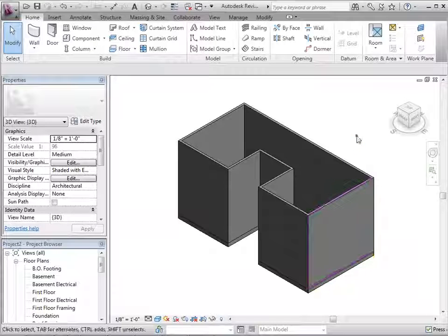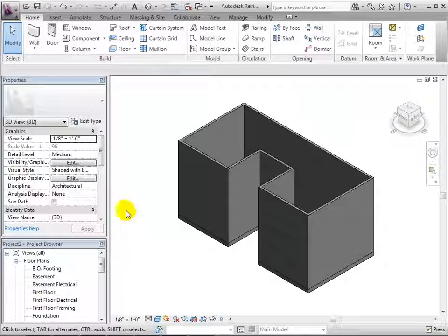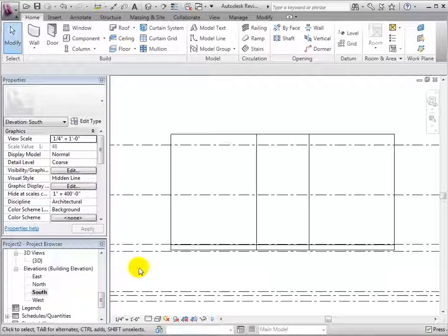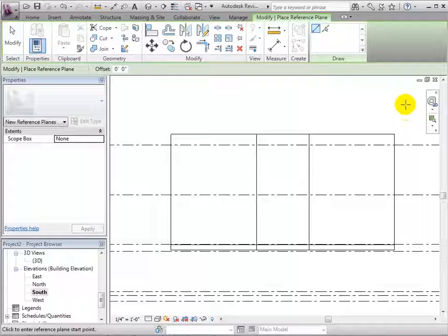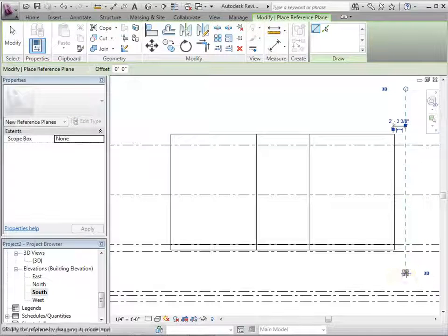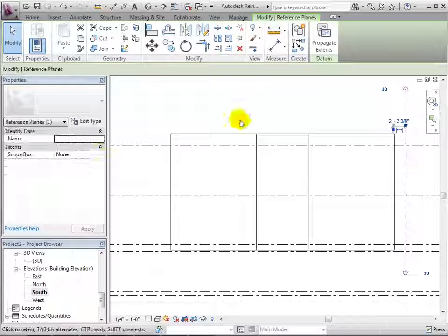Using this structure, let's create a roof from an extrusion. First, let's switch to an elevation view to draw a work plane. This line symbolizes the edge of a plane that is going into the screen. After we draw the plane, we can select it and rename it.